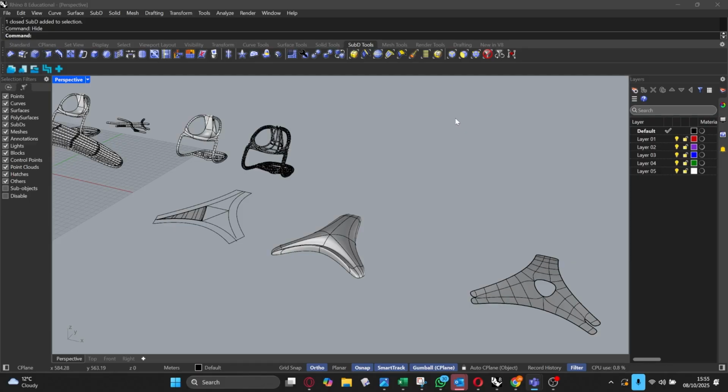I'm talking about boxes or rectangles or things that you can otherwise achieve with platonic geometry. Only use SubD where you reach the limits of what NURBS can do, and you now need to introduce a new tool that will take your work even further. Okay, and it's usually with organic forms.